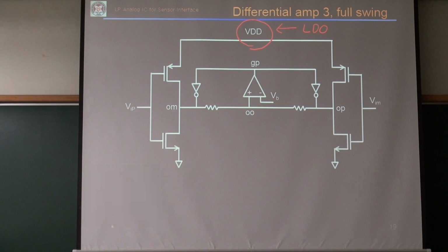Say, the same circuit here. We have around 100K resistor to pick up this common mode output voltage, right? So this should be my common mode output voltage. We can replace these two resistors by a switched capacitor CMFB circuit. Okay, it requires some clocking.